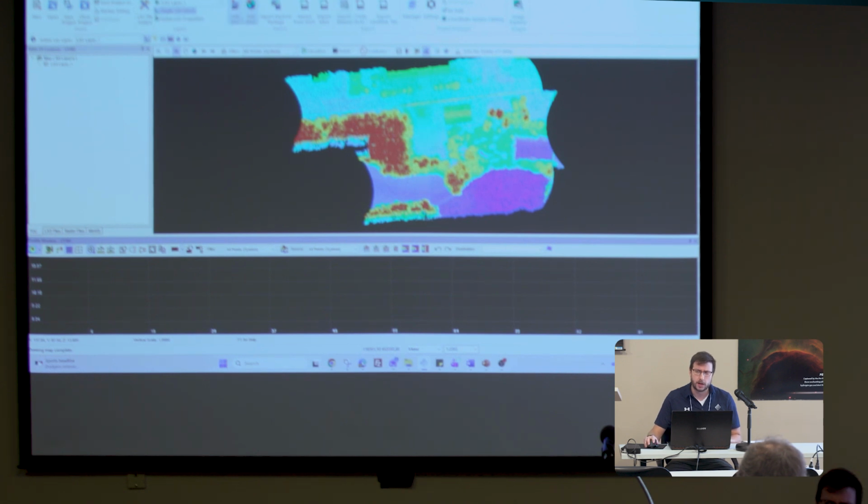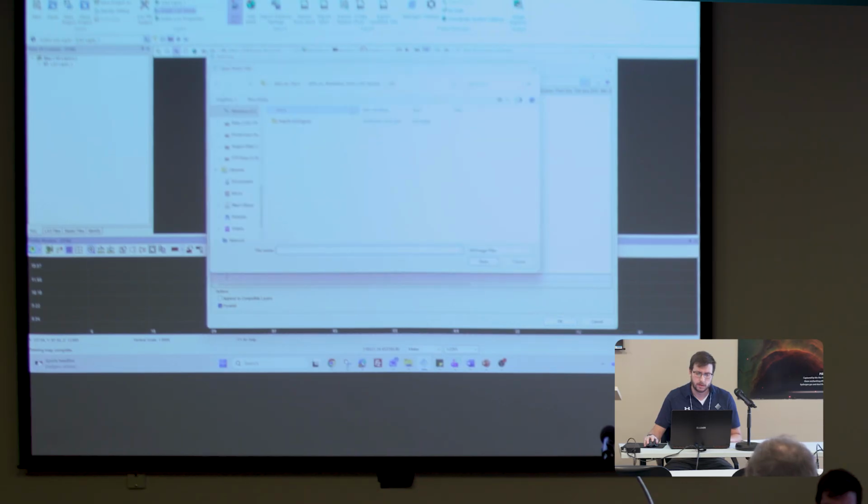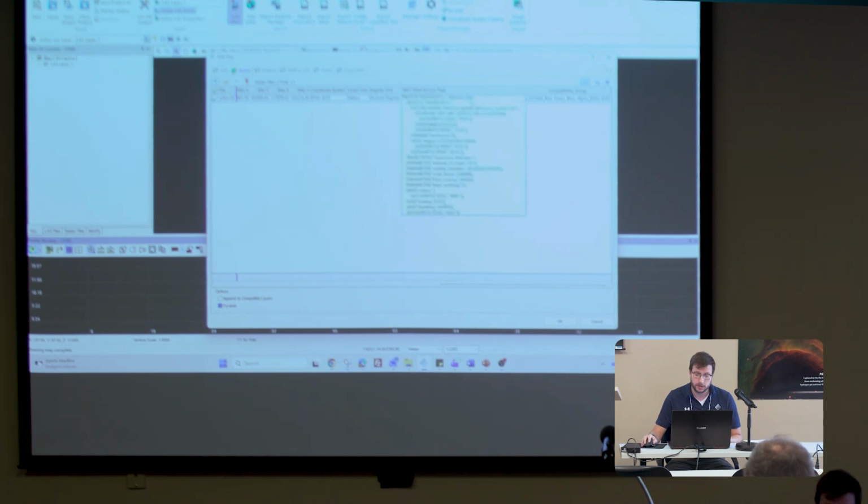Let's click on that Add Files dialog again at the top. And this time let's click on the Raster tab. Click the little green cross, little plus button, and select ortho. Just select the bigger ortho. It's just called ortho.tiff in the ortho folder from the files that you've extracted. Click open. Same kind of thing if we scroll to the right. If the ortho does have WKT, well-known text information, you can see the coordinate system and some other attributes of the ortho.